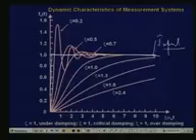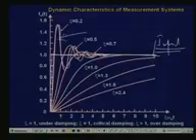Now for different values of zeta, as zeta goes to lower and lower values, you can see that you get an oscillatory behavior. So there is an overshoot. This is called an overshoot. So for underdamped sensors, you are going to get an overshoot. On the other hand, for overdamped systems, there is no overshoot and it slowly rises, almost like a first order system.